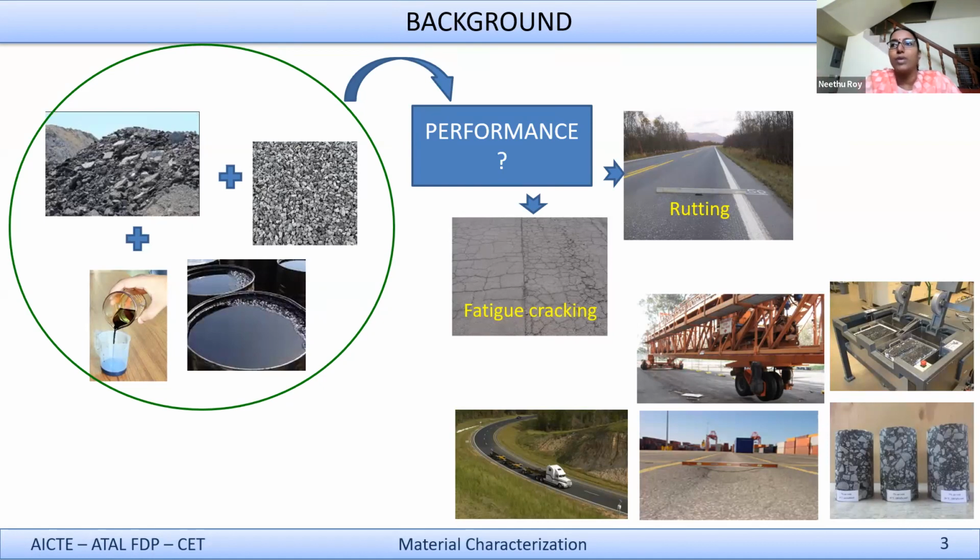Now, if you want to study about the top layer or that bituminous layer that we are concerned about, you can have accelerated testing in the laboratory, which you call like a wheel tracker test or an accelerated flexure test on the material. So that forms the performance evaluation of the mixes in the laboratory.